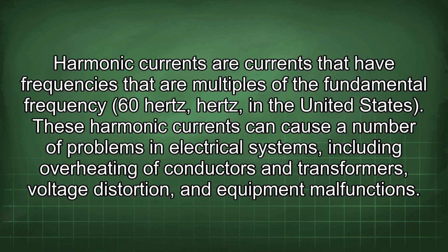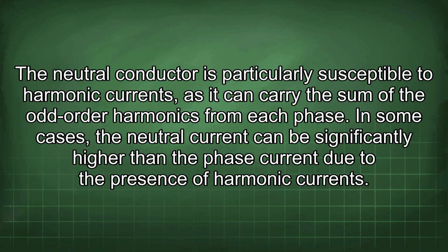These harmonic currents can cause a number of problems in electrical systems, including overheating of conductors and transformers, voltage distortion, and equipment malfunctions. The neutral conductor is particularly susceptible to harmonic currents, as it can carry the sum of the odd-order harmonics from each phase.